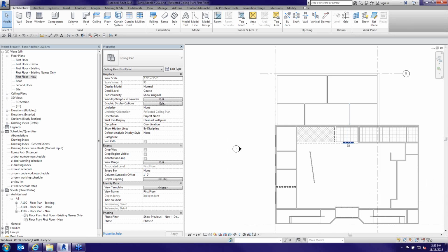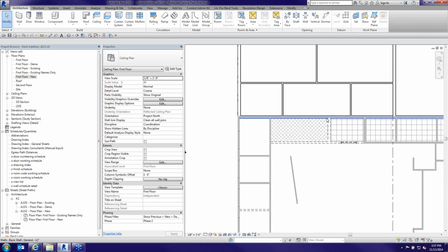I think I caught that one just like I did the wall opening, and wherever I did the wall opening, I just have an opening that I use that's roof-based or ceiling-based, or in my case the opening is face-based, and I just put that in, stretch it, and set it to a phase to be demoed. And then a similar question, how do you demo part of a brick veneer on an existing wall? That actually we didn't talk about.